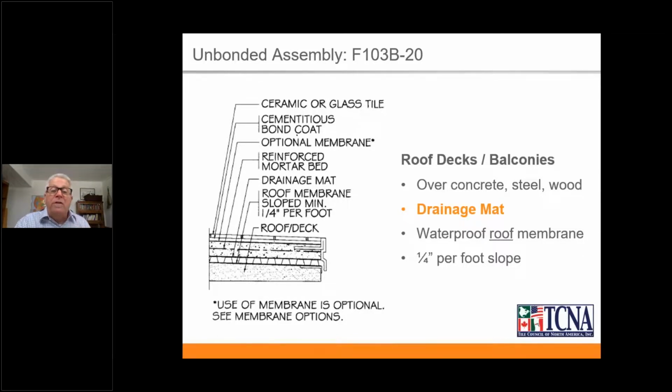These are also going to be very important if you have heated or cooled space, conditioned space underneath the tile assembly, that you have an air gap for the air to get up in there right at what's called the drainage mat layer. And this will happen on the gravel too, to a certain extent, where you allow air to get back up in there and actually dry that out. And if you do get a dew point in your tile assembly, it's on top of the waterproofing, not in the ceiling cavity below it.